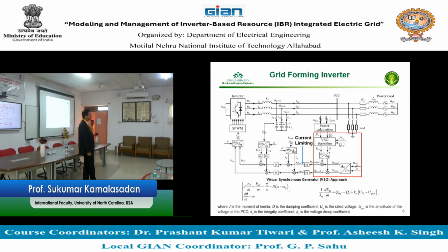Having said that, will you get rid of synchronous generators? No, they're going to be there. One comes from frequency, then goes to angle. The other comes from angle, then goes to frequency. Both of them have to coexist. I personally feel, and there may be different schools of thought, that realistically you will not have a situation in which you work with only angle or only frequency. You have to work with both, and both have to coexist.